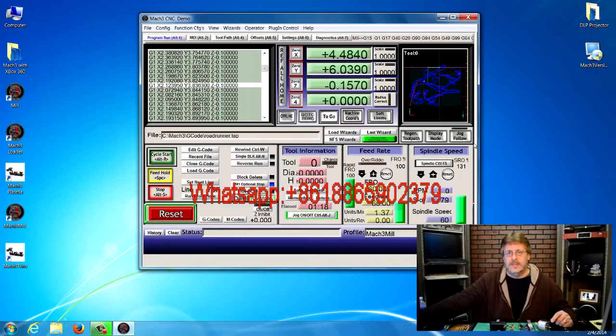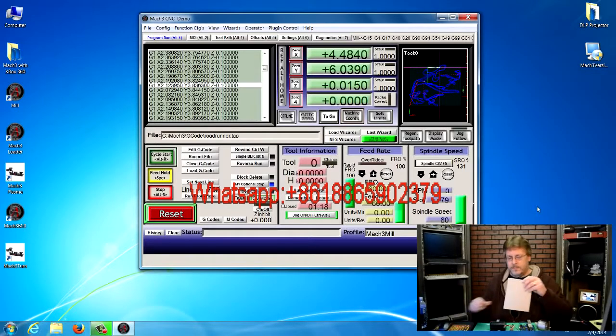And then to move the Z axis, the actual spindle up and down, you can use the page up and page down. Now, if this machine were actually hooked to a CNC machine, my actions on the keyboard would actually move the machine around. If I want to return home, and I had mentioned in another video that every machine has a home position, if this were a piece of wood that I was wanting to cut, most generally you would reference one of the corners or dead center as a home position, and that home position is where you would start and stop every time.